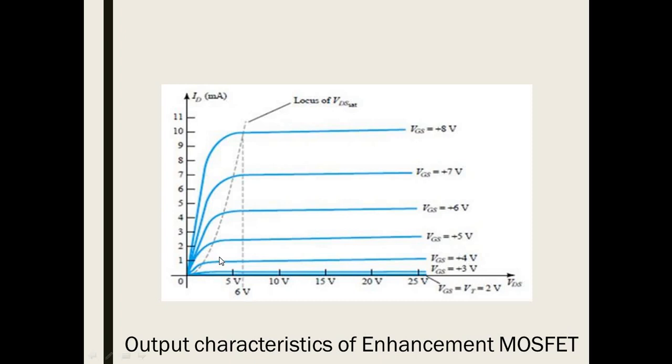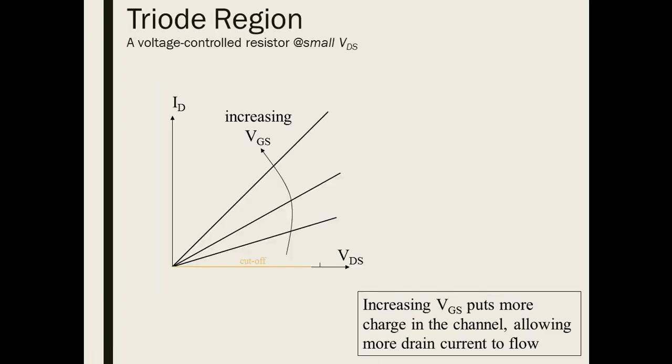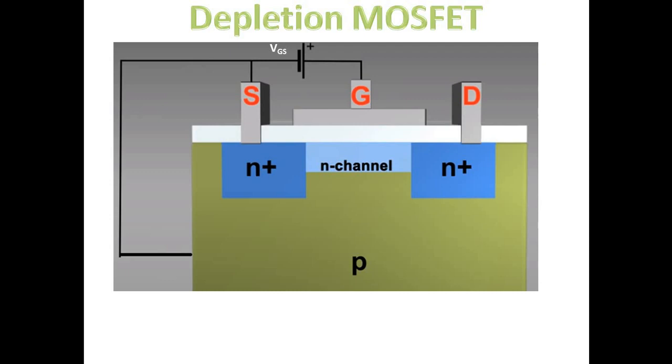Okay, so today we will discuss the other side of the story, the depletion kind of MOSFET, and gradually you will understand the major differences, not only construction-wise but also working-wise, between enhancement type operation and depletion operation. So the depletion MOSFET is a structure quite similar to the JFET, because here you have this N channel.